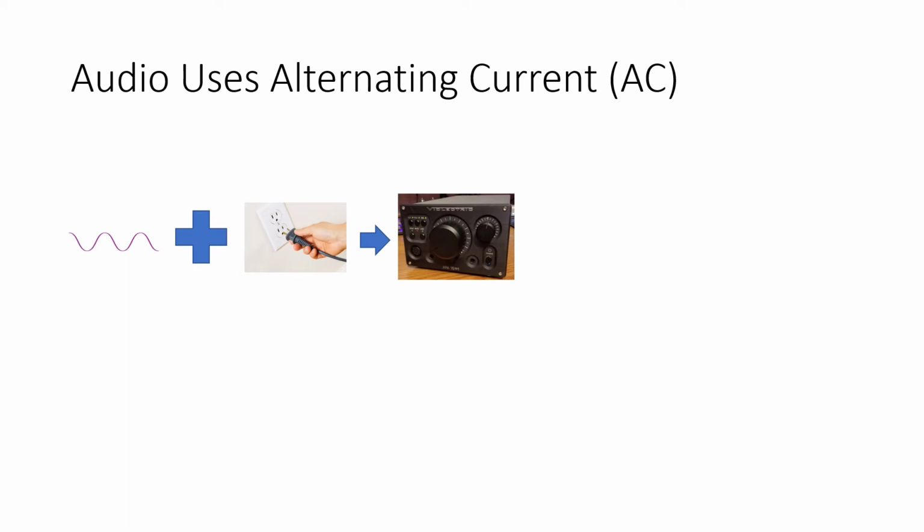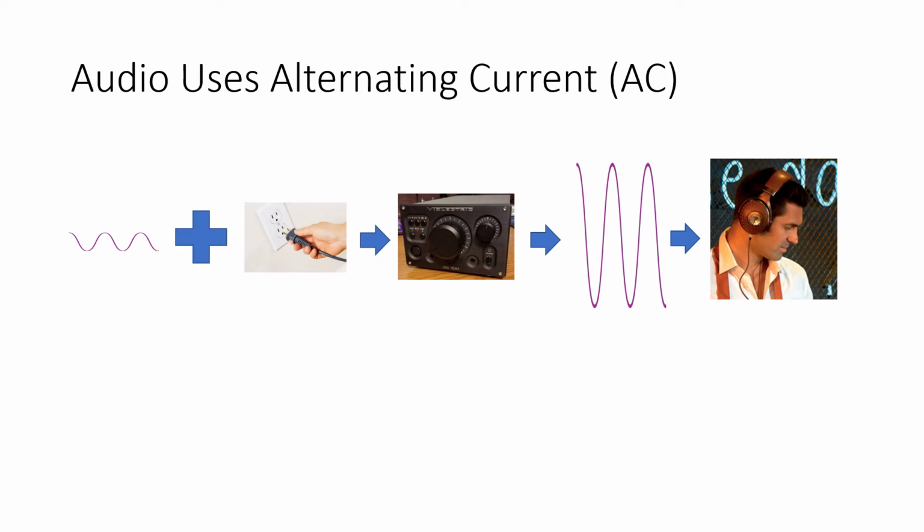And your audio amplifier is taking that signal and that electrical energy from your power plant and combining them together to increase the amplitude. Amplifier, amplitude, pretty clever how they did that, right? Okay, to increase the amplitude of that electrical signal, which is modeling a sound wave. And then it delivers that higher amplitude electrical signal to a speaker or headphone driver, which then vibrates back and forth in air and creates a pressure wave that travels to your ear,